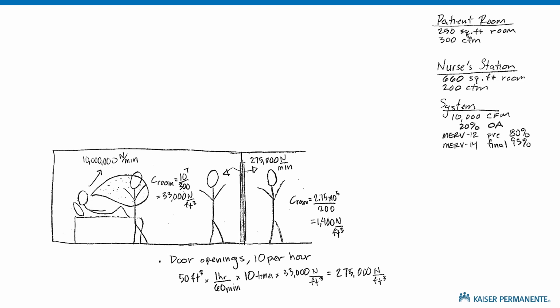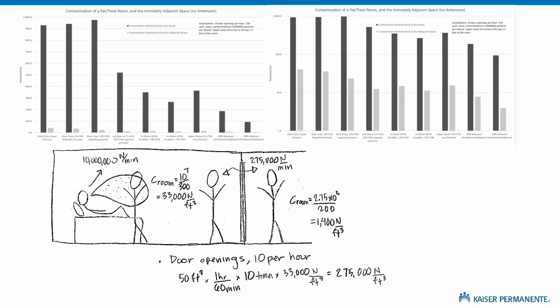And now I'm going to break character and get away from these hand-drawn slides. Fun while it lasted, but now we show a spreadsheet. The units on the y-axis here are particles per cubic meter, which is kind of the more common unit, particles per cubic foot, not really used anywhere. The bar chart on the left is at full scale, and then the bar chart on the right is a logarithmic y-axis. I would normally look at this as a logarithm because you're really looking for those 1 log, 2 log, or 3 log effects.